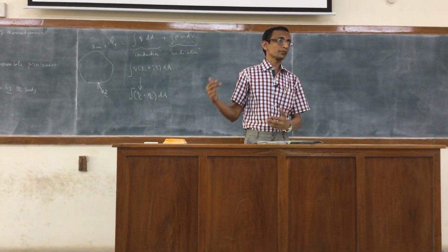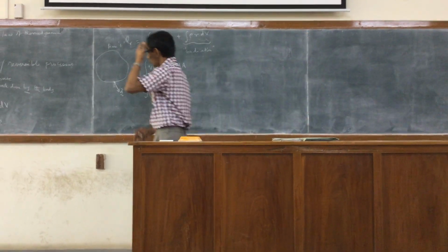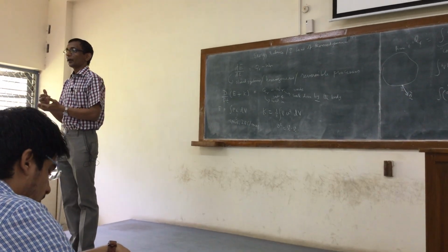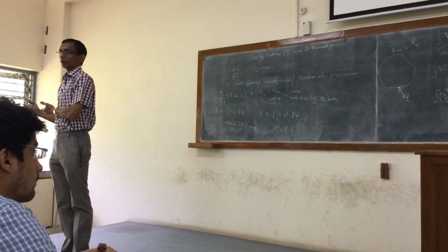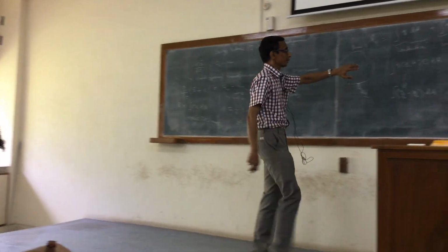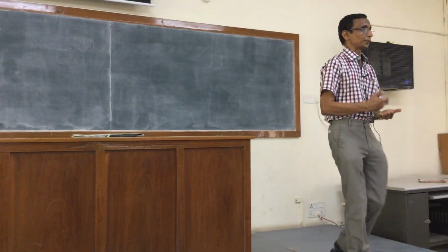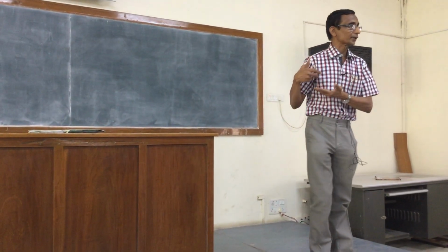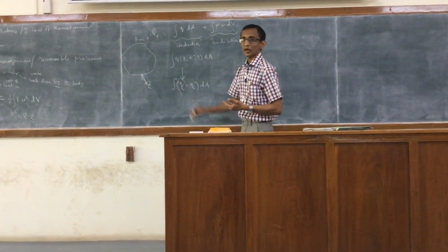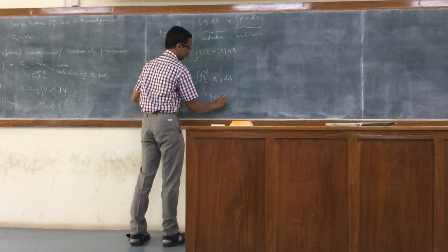So this is the exact analog of Cauchy's stress theorem. Interestingly, it was proved by Stokes almost 30 years after Cauchy proved it in a more complicated case. There, you have a stress vector which is dependent on the normal, and you have to prove the existence of the stress tensor. This is easier to do because the heat flux is a scalar, and we have to show that its dependence on the normal is given in terms of the dot product with the flux vector. So this is really a function of x and t.